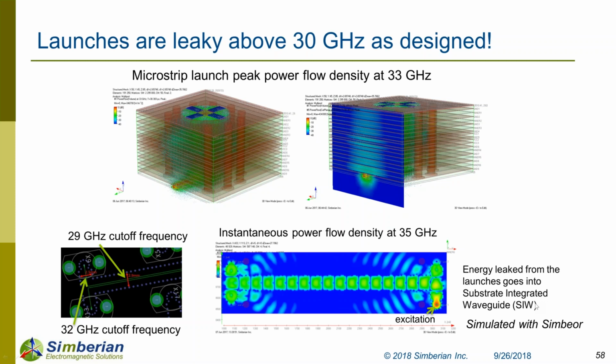So that's basically my mantra now: you have to design only the structures you can reliably predict. Some people assume that they can easily predict stripline behavior without even stitching vias or anything like this. That used to be true, but if you move into the microwave and millimeter wave domain, it becomes a completely different picture. So you have to establish structures that you can really predict, and the validation boards are a tool to see what can be done in this domain and how to keep it predictable.